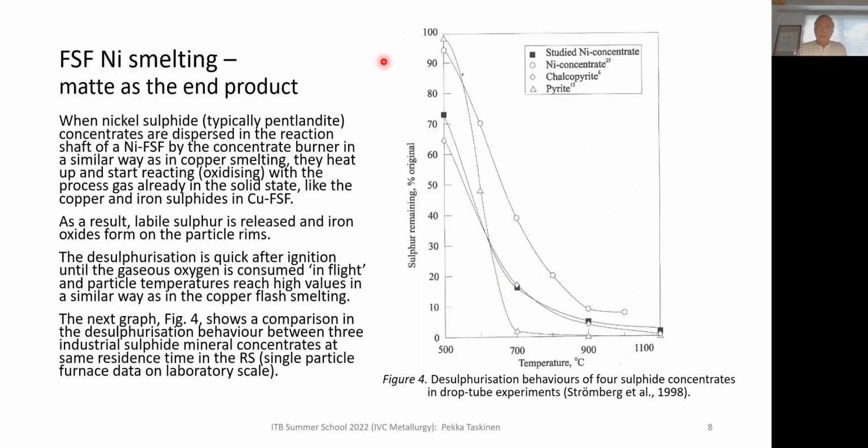At some point, when the particles are heating up, their ignition point is reached, and they start burning very quickly, within tens of milliseconds. A particle typically of the size of, say, 40 microns in diameter, on average, is combusted from sulfidic state to fully oxidic state, depending on how much oxygen is available in its surroundings.